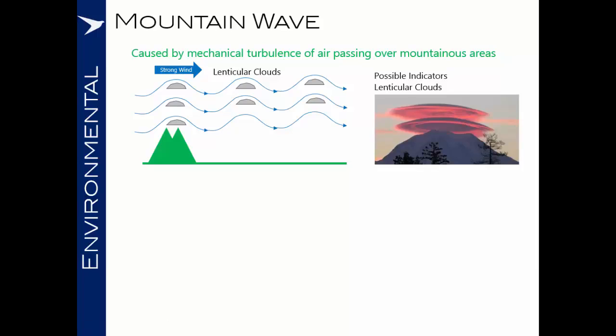One of the indicators of particular danger associated with mountain range are the rotor clouds, which tend to occur lower down and form by a drop in pressure caused by rotating airflows towards the lower portions of the mountain wave. But note that the clouds are not a reliable indicator and may not always be present.